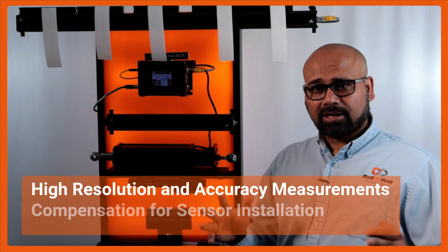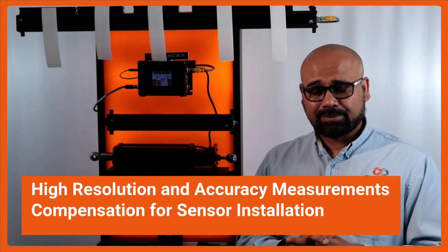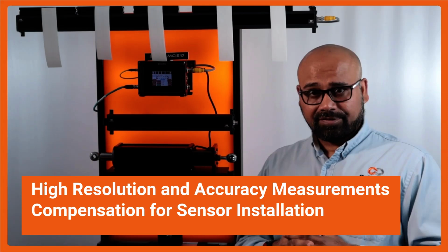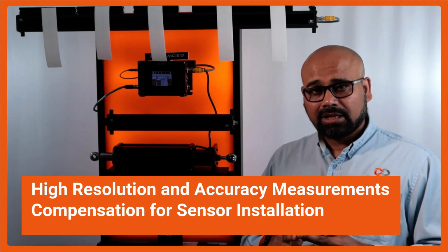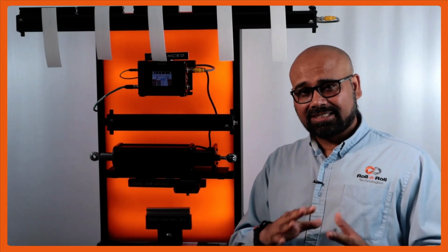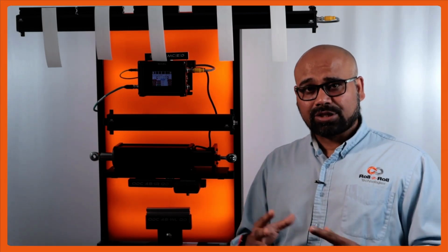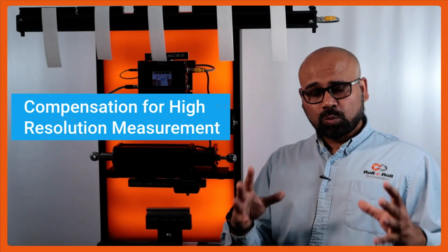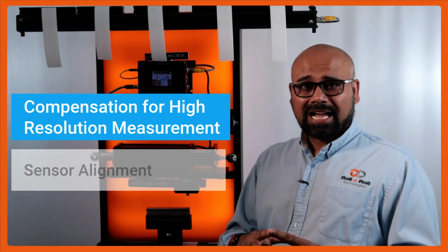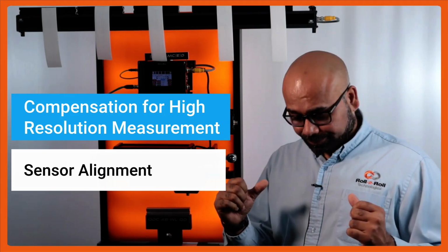For customers that are looking for really high resolution measurement and high accuracy measurement, we also have other features to compensate for the installation of the sensor. In the previous section, I talked about the brightness, the contrast, and all those kind of things. But on top of that, if you want to get a really high resolution measurement, then there are a few other things that we can compensate for. One of the compensations is for how the sensor is aligned with respect to the machine.